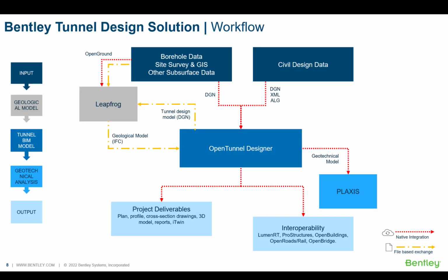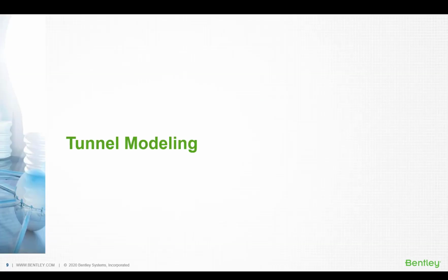In more detail, borehole data feed through Leapfrog into OpenTunnel Designer. OpenTunnel Designer then models soil strata and the tunnel with the survey and alignment directly imported or referenced. Plaxis can then perform geotechnical analysis and design by extracting the model from OpenTunnel Designer. Project deliverables are directly extracted from OpenTunnel Designer. Now we can look into the tunnel modeling in OpenTunnel Designer.